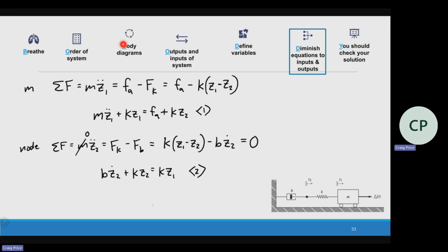So in total it's third order, because this is second order and this is first order. There is no acceleration because there's no mass. So that one's kind of a tricky one. I didn't really know at the beginning. It's okay to just skip it and move on, but with these degrees of freedom, we have different sums of forces. I want to make sure we do that, so that's what's going on here. Third order system.